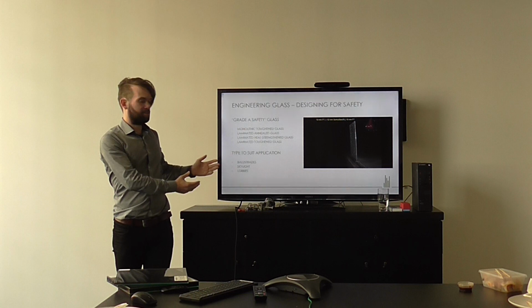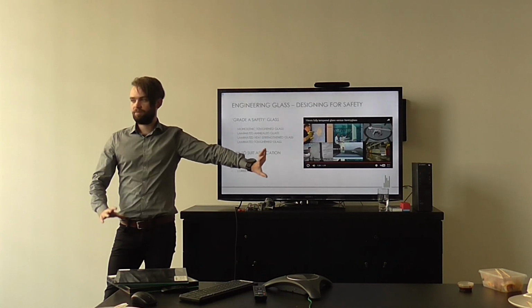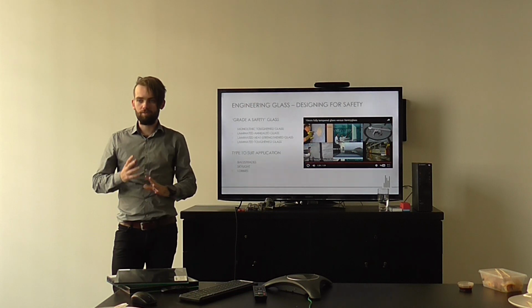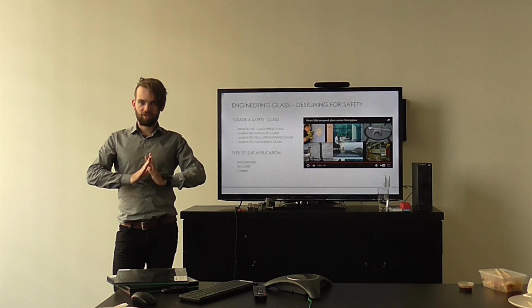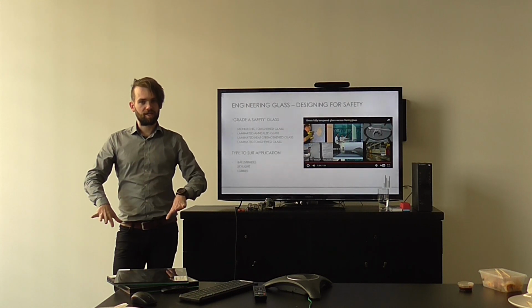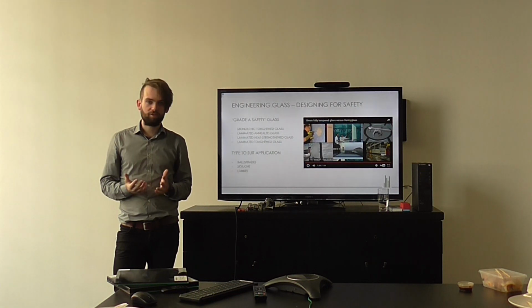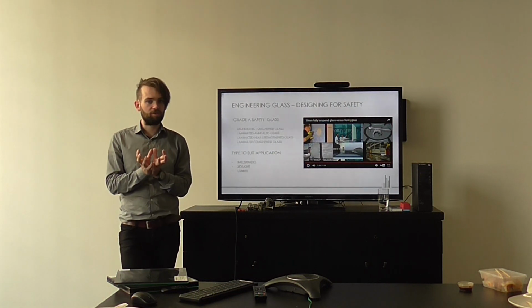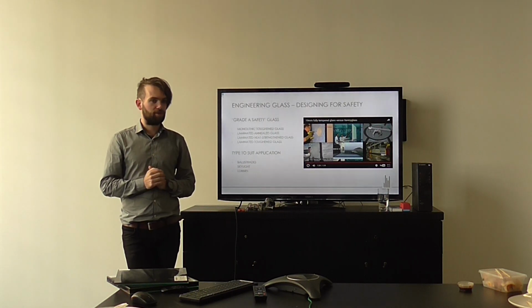So the whole point of this was just to touch on that, yes, those are the four types of grade A safety glass we have, but in terms of where we use them, we do need to think a little bit sometimes about this. What I spoke about in terms of toughened laminate breaking and falling like a sheet, similar behaviour is not observed with heat strengthened or annealed glass because the larger particles tend to lock together better.